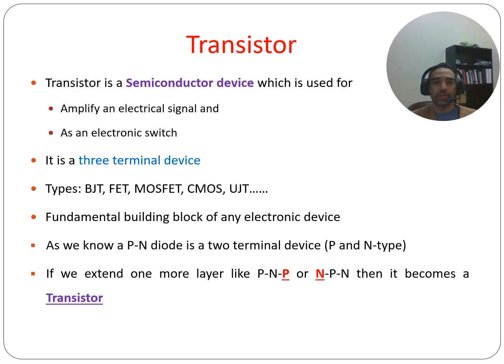that we have available. So going from something like a diode to a transistor, remember that PN junction diode? It has two layers, the P-type and the N-type. So you add one more layer and you get something like a PNP or an NPN. And when you do this, you turn a diode into a transistor. And this can do a lot more than what a diode does. It can amplify and it can act as a switch.